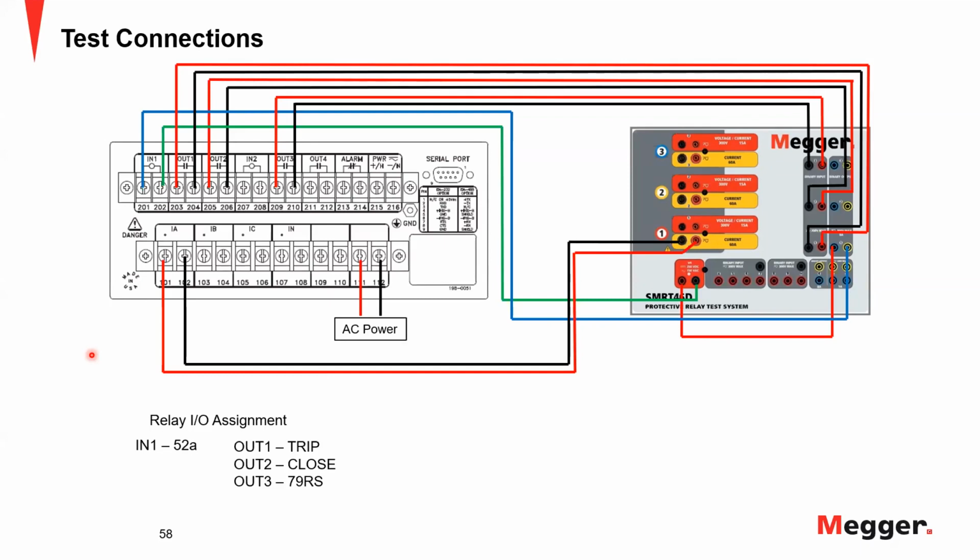Thanks. So our next question is going to be for Sugosh. Do some test templates exist for reclosing tests in the RTMS? Yes. What we have is, like you already saw what Mike showed, we have the state sequencer feature that by default is set up for a 2-shot lockout testing. And we also have these test templates that are embedded in the relay test plans. Based on the settings you read for the 79 element, it is going to automatically configure the template for your testing. So yes, we do have the templates.